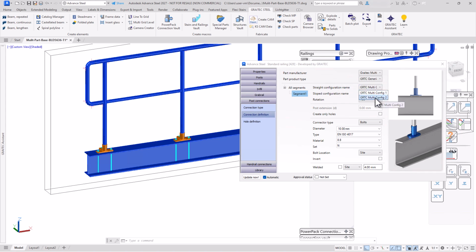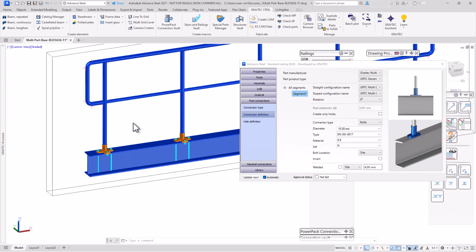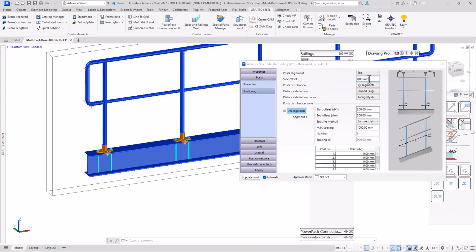The system creates a different arrangement suited for beam connections. In some cases, the initial orientation may appear incorrect. Adjust the rotation to correct the alignment. If the connection is positioned above the beam, apply an offset. Offsets move the base connection to align correctly with the beam flange.